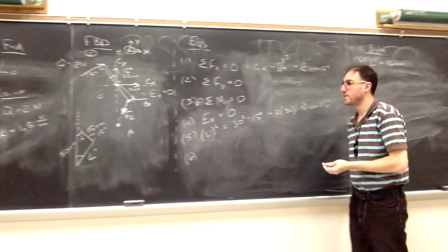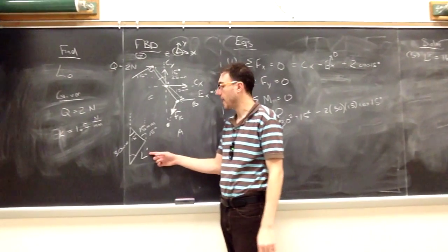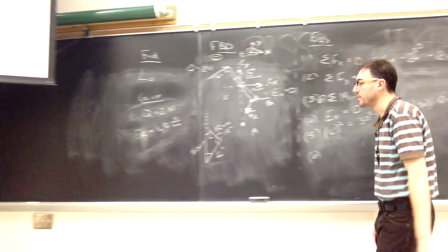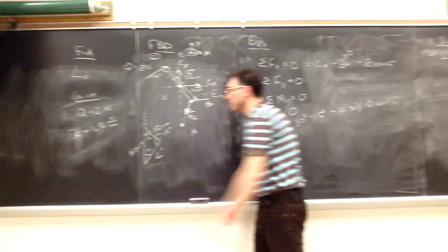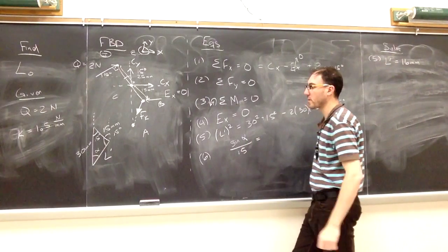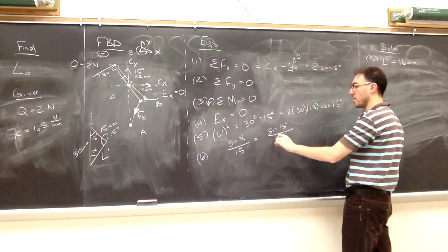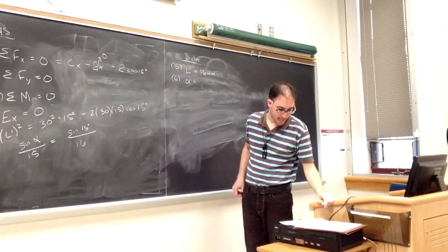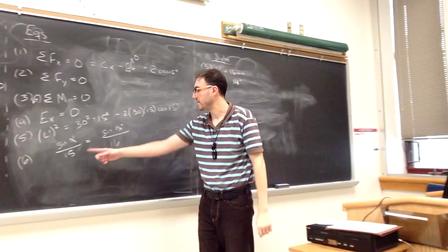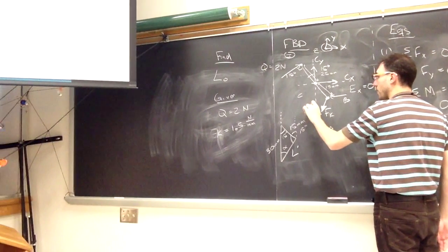Here I can use law of sines because I know the same reasoning that I used last time. L prime is not the longest length I have, the 30 is. So if there's an angle that's obtuse, it's going to be this angle here. So law of sines is fine to use for this. I'll call it alpha, because I know it has to be acute. The sine of alpha over 15 is therefore equal to the sine of 15 degrees over its opposite length, which was L prime, which was 16 millimeters. That tells me that that angle alpha is about 14 degrees. It should be pretty close to the 15 since these are pretty close too. So we'll call that a 14-degree angle, which means that this is 14 degrees here.